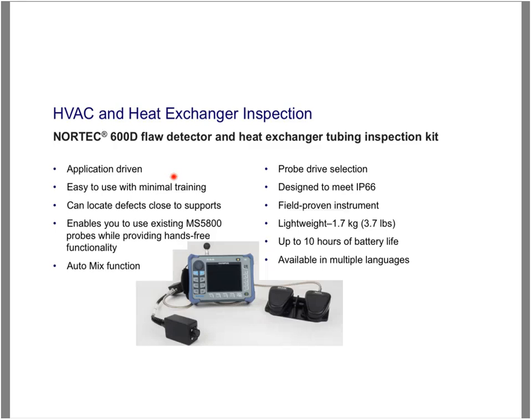You can get a lot of battery life. If you're doing eddy current testing, it's about 10 hours. If you're using remote field, it's a bit less because the remote field adapter is amplified. You might get between 6 and 8 hours. And the other thing is the interface has been translated, so it's available in multiple languages. So if English isn't your first language, no problem. We have many other languages: French, Chinese, Japanese, etc.